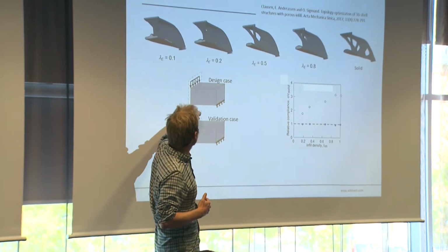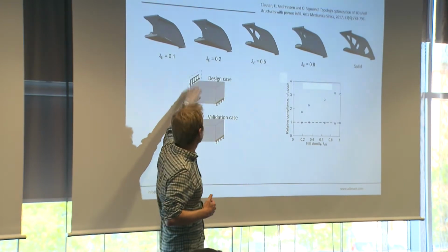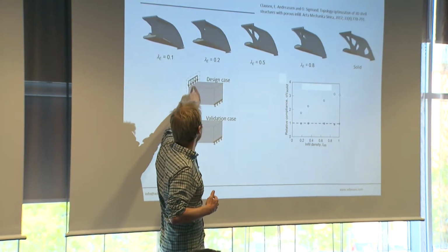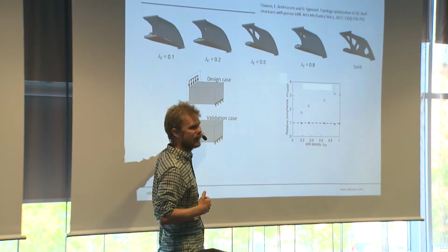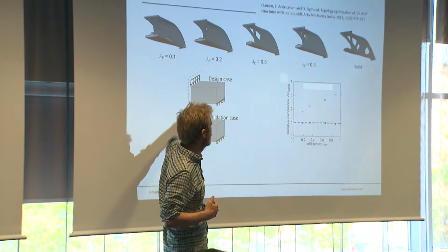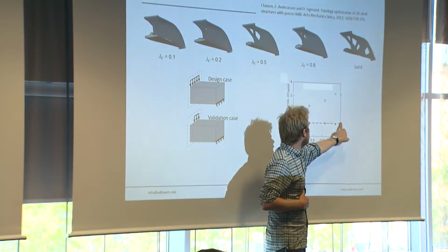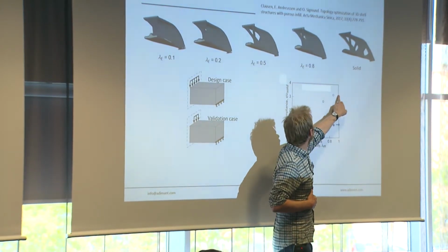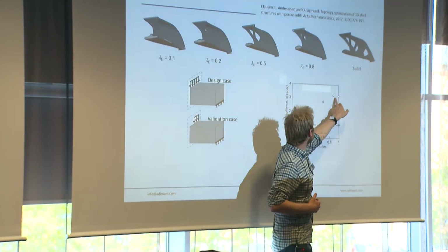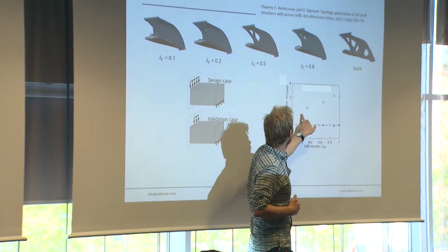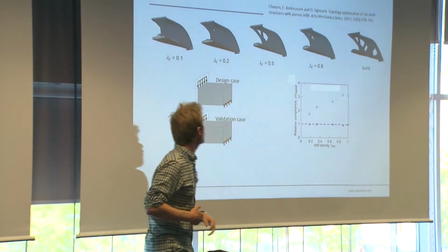But if now we only apply the force at 1/2 of the part here, so it's optimized towards this load case, but if we now test how my part will perform if the load case is like this one down here, where I only apply it at 1/2 the length, then you'll see that my totally solid design performs much worse. It's better to be low. So this is this one here. But as I increase lattice structure, the performance closes in on what we try to optimize towards.